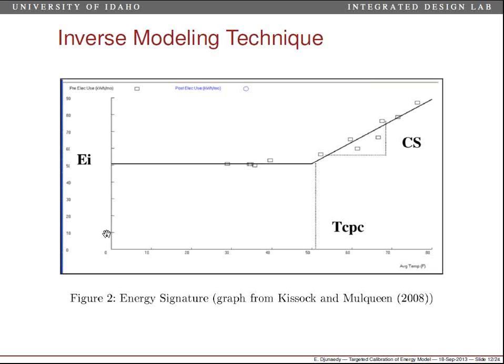You will have the energy data on the vertical axis, and you plot it against the horizontal axis, which is not time, but outside air temperature. So if you have the January energy bill, for example, this point, you plot it at the monthly average temperature of January. Very easy. You take all the outside air temperatures throughout January, not inside, outside air temperature, and average them. Boom. You have that, put it there, and put your energy reading right there. One at a time, 12 months.